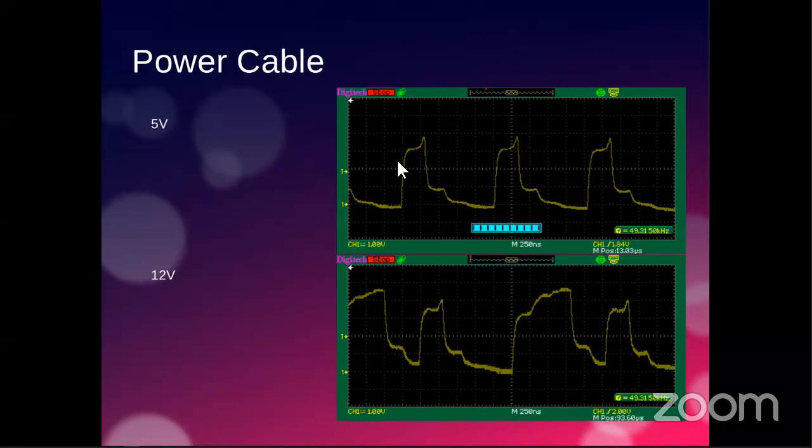So the signal starts to rise, it reaches a certain point, it plateaus, and then it only spikes at the end. This is going to make this thing incredibly sensitive to VDD. Because if VDD is such that 0.7 is up here, then it's not actually going to read the rising edge until right at the end of the signal. In the case of a 1 here, you can see that on the 12 volts, there are no 1s here. These are all 0s. You can see here with the 1, it's probably going to read the 1 here.